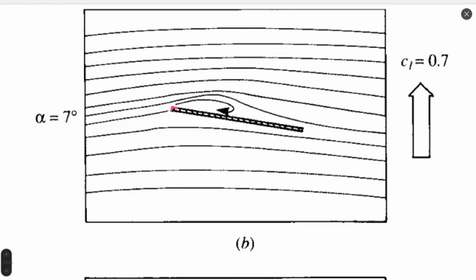Subsonic aerodynamics, and especially incompressible aerodynamics, does not like sharp edges. Everywhere where sharp edges happen in front of flow, it will start to create a vortex associated with this sharp behavior. So flow will start to become smooth. This is why it is creating a bubble around this sharp edge.